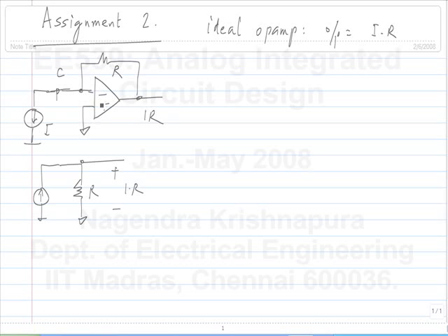When I have an op amp of gain bandwidth product omega u, what is the output? If the op amp has a finite gain bandwidth product, what is the output of the trans impedance amplifier? I is not necessarily DC, okay. This is what I mean. No, the unity gain frequency is omega u. So the transfer function of the op amp is omega u by s.